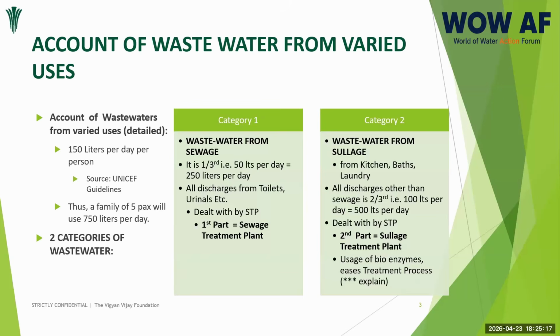Of course, you cannot bring it to a potable level, but you can always bring it to a level in which it can be used for secondary uses. In the complex, that water will be fairly clean and clear to be used for flushing toilets and for gardens. Because it's already rich in organic ingredients, you will find that water is really good for plants. So the outlet will be limited to around 30 ppm. Next slide, please.